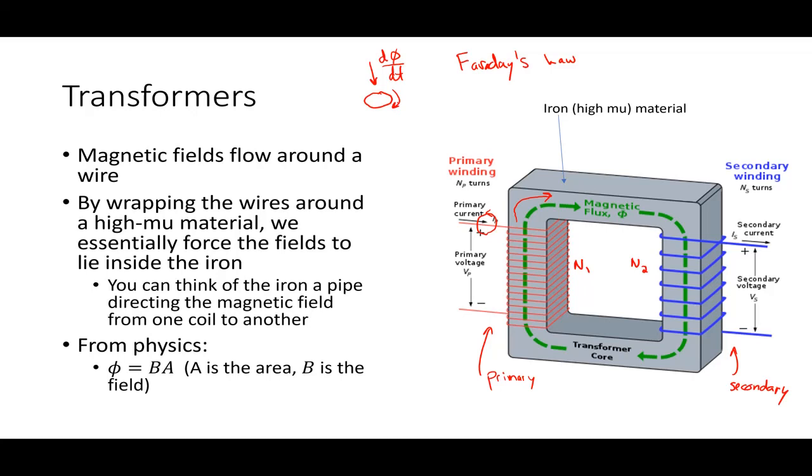That's the basic principle that AC power generation is based upon. So in this case, if I put an AC current into the primary right here, I'm going to get an AC current induced in the secondary. It's like I have a transmitter over here on the primary and a receiver over on the secondary that generates a new voltage.